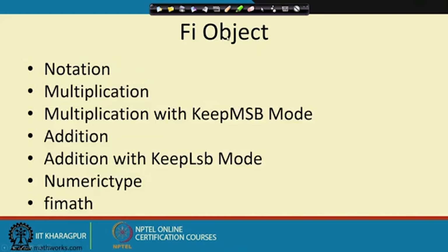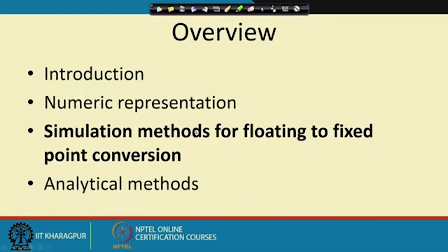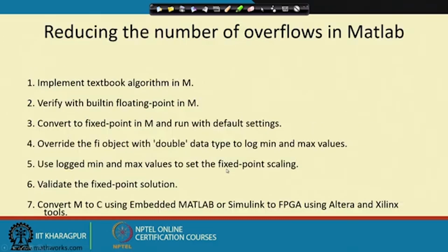Okay. So, this fi object can be implemented for multiplication, keeping the keep MSB mode, then addition with keep LSB mode, then the numeric type. So, these are the things which you can do in MATLAB using the fixed point toolbox. For finding out overflows, there is one algorithm, which I think is inbuilt in MATLAB.